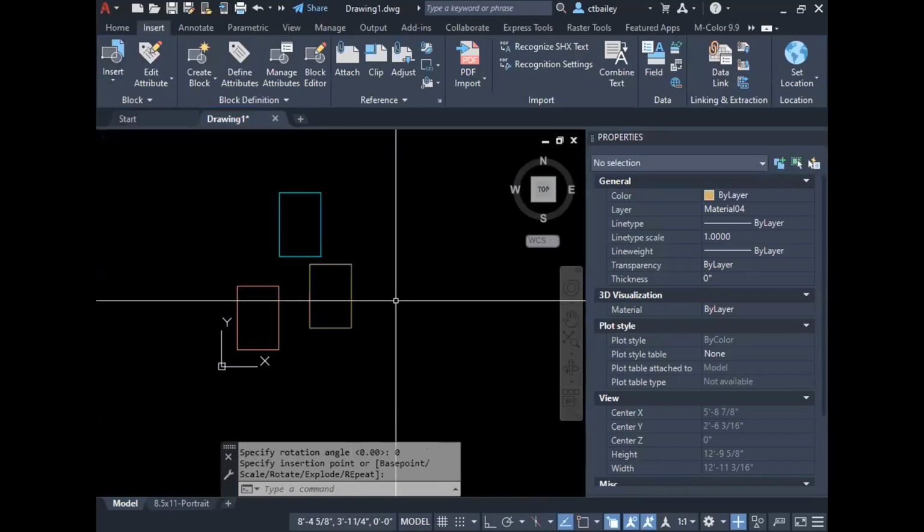Okay. In other words, when you use layer 0 when you're defining your block, the stuff in your block, i.e. line segments, pieces of text, arcs, circles, anything, if they're selected as layer 0 inside the block, they're going to appear as your current layer when you insert it.